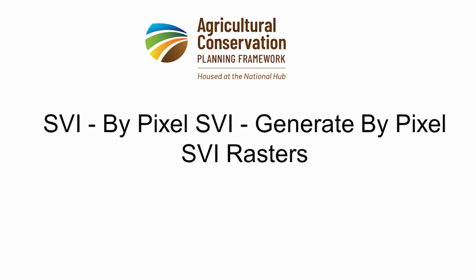tool. The Generate by Pixel SVI Rasters tool combines map unit soils information with high-resolution topographic information on a pixel-by-pixel basis. This data integration allows for the generation of SVI vulnerability surfaces at a resolution equal to that of the input DEM, enabling landscape characterization to occur at scales other than the soil map unit.